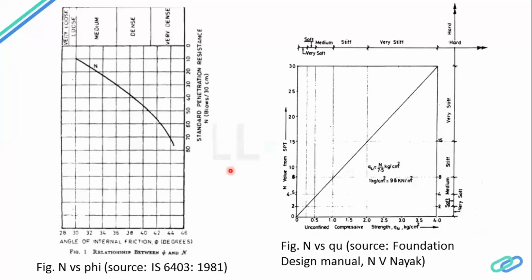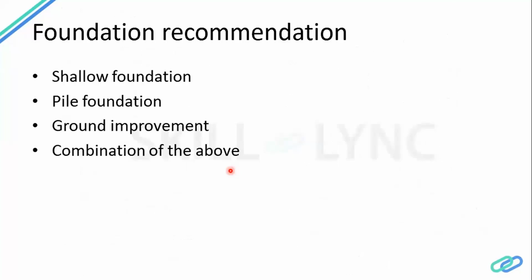So as I have told, we have covered what is the soil investigation procedure. So after this investigation is done, the agency will be giving us a soil report. The soil report will cover what is the type of test, what is the purpose for which that's performed. Then it will include this bore log sheet what we have seen, then the lab test results performed, also the supporting graphs. Then they will give what is the foundation recommendation. So we will move on to foundation recommendation part.